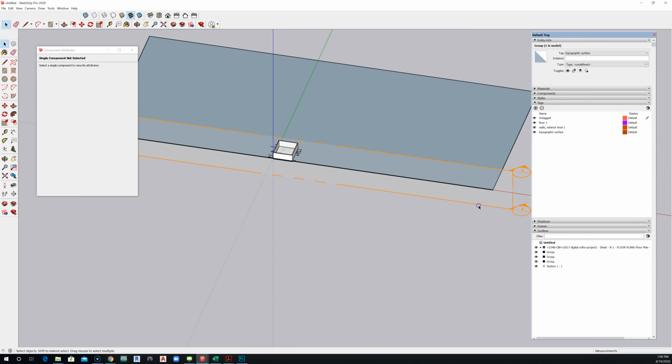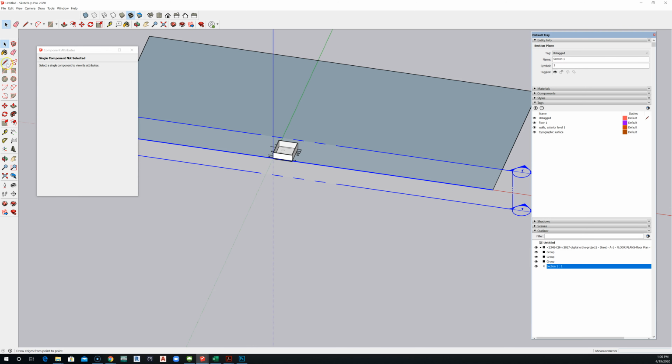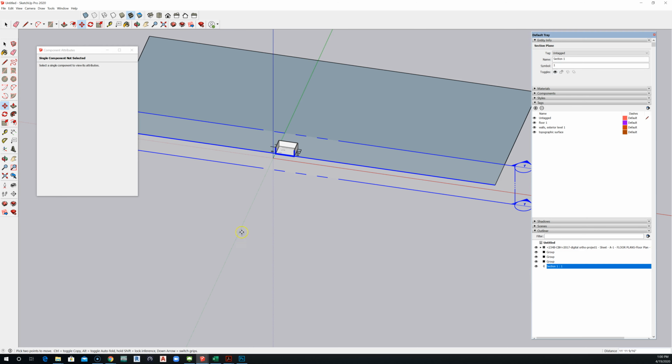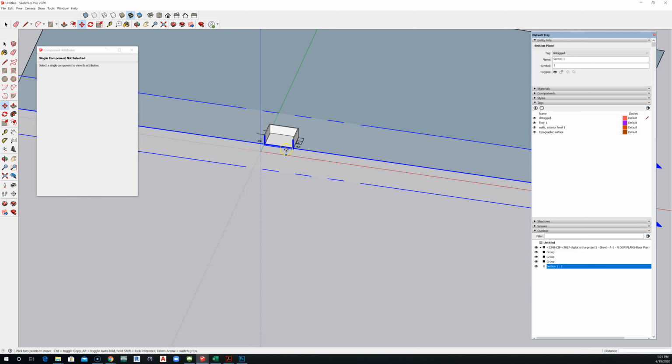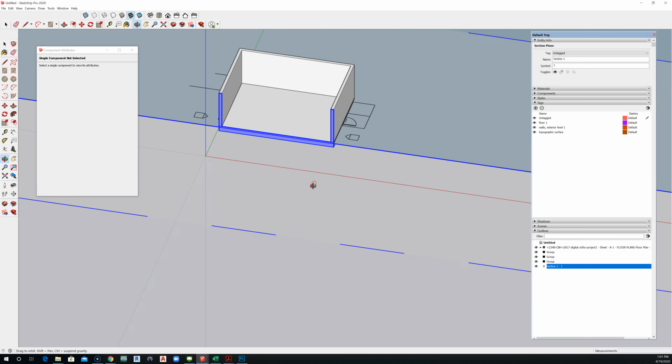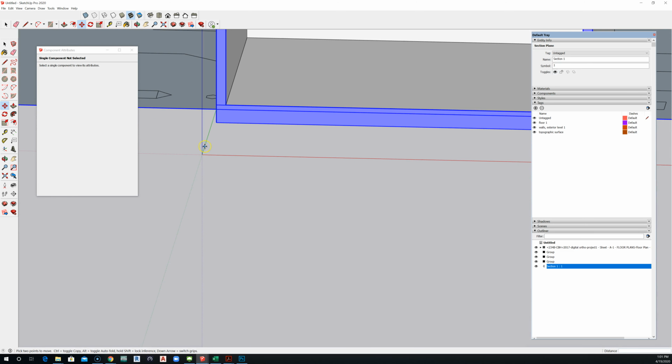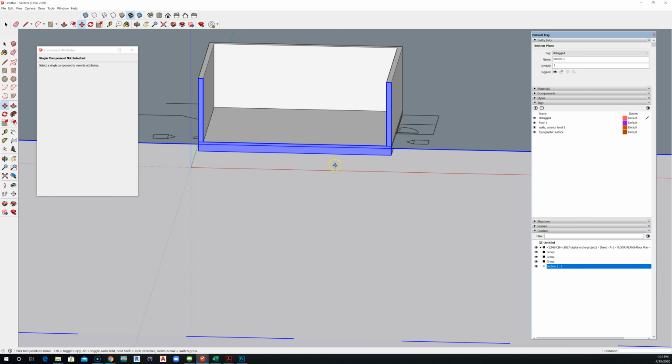And I move that section plane somewhere inside my model. So you see what I've done here? I have site topography at elevation 0. The floor extends 4 inches above elevation 0 and 12 inches below it, and my exterior walls start at an elevation of 4 inches.